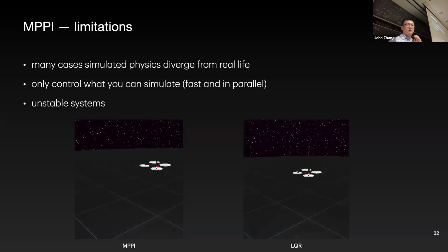Sorry, does the instability in MPPI for hardware control come from model mismatch? No, it just comes from the dynamics being unstable. Basically, the dynamics have large eigenvalues. One way to think about this is that MPPI is doing single shooting. So if your A and B matrices have large eigenvalues, and you multiply them across some time horizon, you eventually get really, really bad ill conditioning, meaning that you lose numerical precision and can't really do anything at that point.